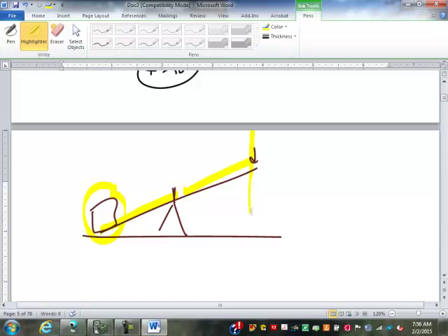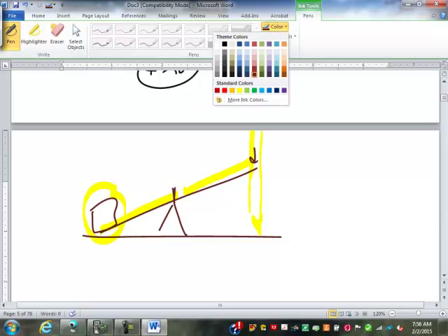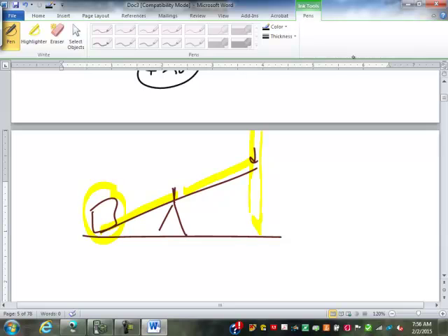Well, there might be, because gravity helps me when I'm pushing down, right? Sometimes, even though the mechanical advantage doesn't reduce the amount of force you have to put into it, changing the direction helps. Sometimes it's easier to push than it is to pull, or easier to push down than it is to lift up, changing the direction of the force. Other things, mechanical advantage less than 1. Sometimes you want things to move faster. Well, you make them move faster, you have to put in more force to make it happen. Things like that.